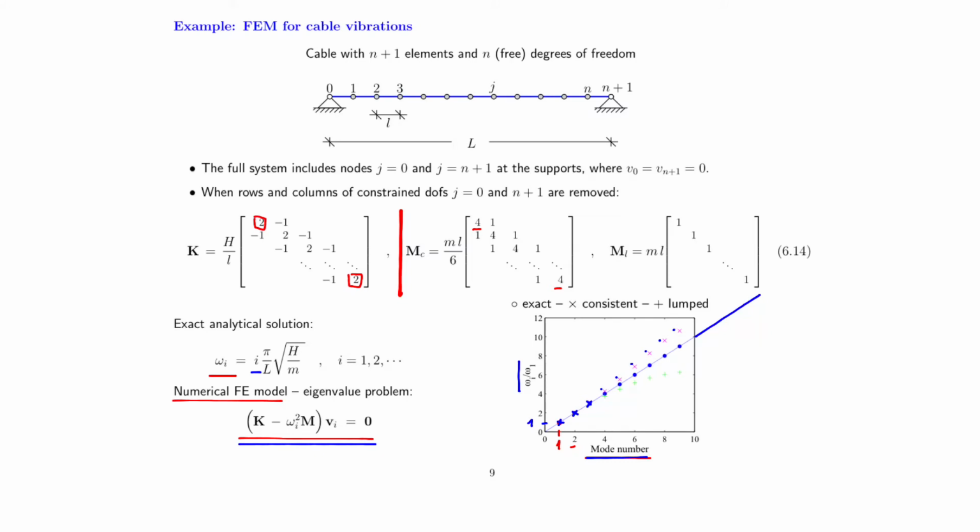And that is simply because for higher modes, we have many half sinusoidal waves in the corresponding mode shape vector, and suddenly we see that for a given half sine, we now only have 2 elements. And the rule of thumb is that for a given half sinusoidal wave, you should probably have no less than 3 to 4 elements.